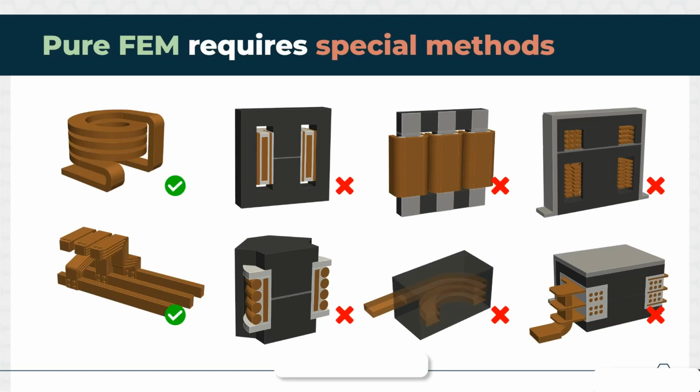For example, the dual-active bridge has litz wire, so we need a litz wire model. In this case, a 3D phase choke with gaps, we need a foil winding model. As well, at higher frequencies and higher harmonics, we need special models called stack models, lamination stack models, to account for magnetic fluxes in the laminations and eddy effects inside. Here, we would need circuit models in order to connect those individual turns, and so on and so on.